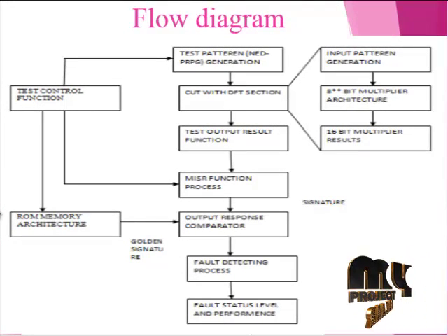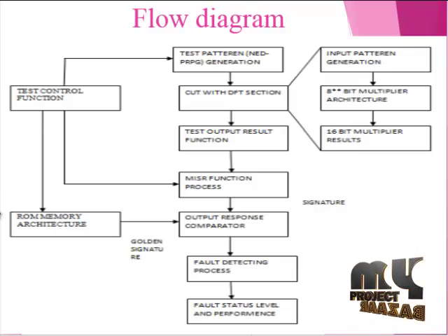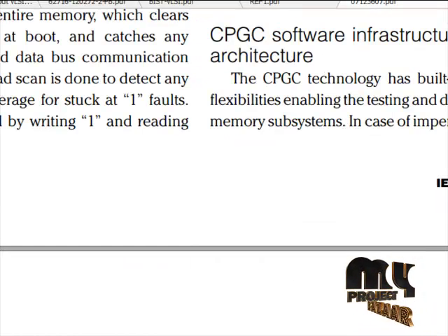A quest to achieve higher BIST fault coverage with shorter test application time generated an immense amount of research. The pseudo-random test sequences were modified either by placing mapping logic between the generator outputs and inputs of a circuit, or by adjusting the probabilities of outputting zeros and ones so that the resultant vectors capture characteristics of test patterns for hard-to-detect faults. We use a multiple-input architecture for the 16-bit output result in the DFT section. The architecture has built-in customizable flexibility enabling the testing and diagnosis of entire memory subsystems.